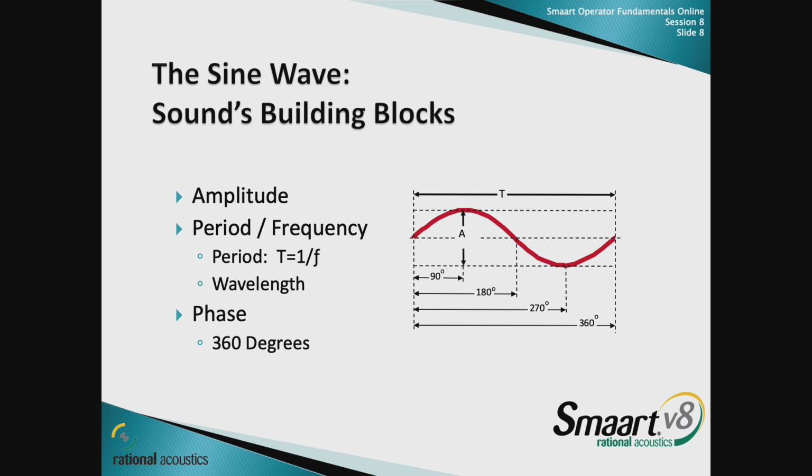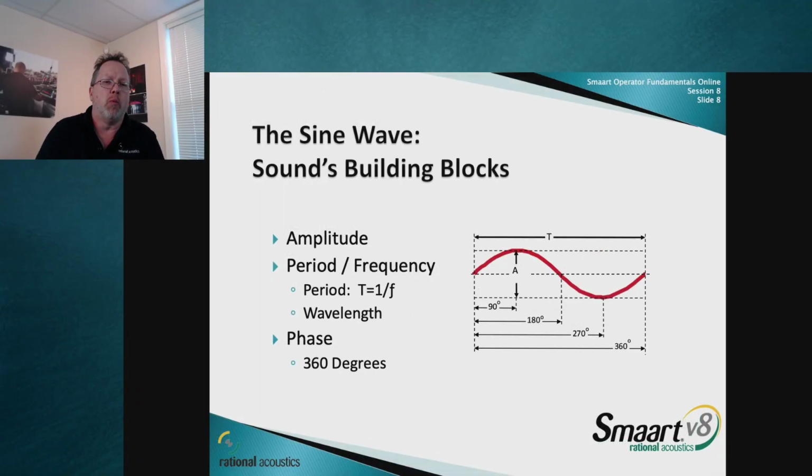There are a couple of things that describe the sine wave. One, it's an oscillation. It's just a repeating function. It's an oscillation in pressure that we convert to an oscillation in voltage, and then we digitize it and have an oscillation in level. But basically, it's just a repeating function. So the first piece of information we want to know is how long does it take to go a full cycle? That's the period of the wave. 1 over the period is the frequency.